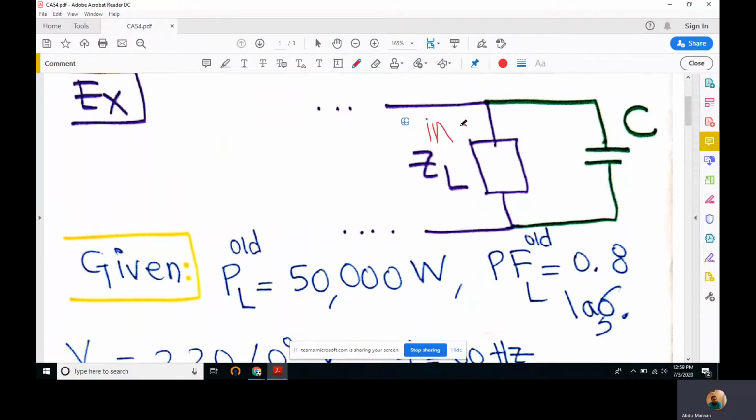This means they have lagging power factor, and as the amount of inductance increases, as we discussed in the last lecture, power factor goes down. It should ideally be 1, but it goes down. So we need ways to improve it and bring it closer to 1.